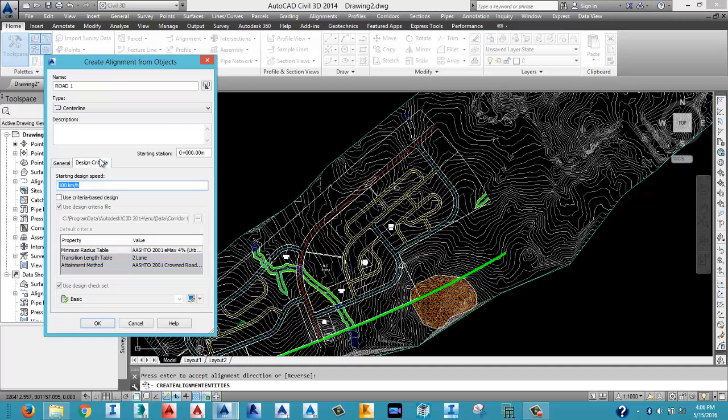Another design criteria on this tab is the speed, depending on the standard. Well, we always have a standard. The Federal Ministry of Works has a standard we use in design. The Federal Capital Development Authority, that's FCDA, and FCTA have the standard for their various road hierarchies. State ministries too have their own design speed, so you input those design speeds accordingly.